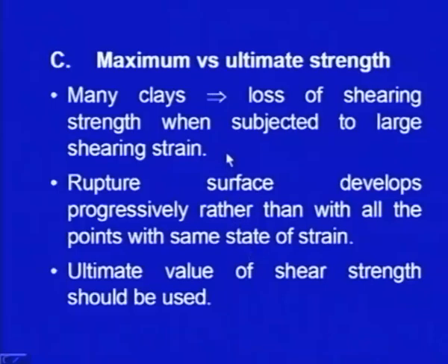The next point which you will have to answer is whether we should use maximum shear strength or the ultimate shear strength. You will find that it happens in case of the clays especially, that as the shearing strain increases, the soil loses its strength. If you draw stress strain curves, as the shearing strain goes on increasing, the strength goes on decreasing.